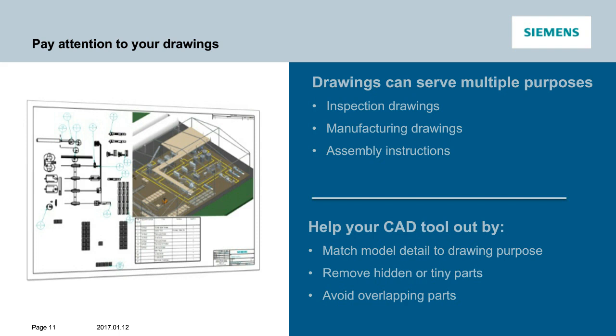The problem with detail is that it is costly in several ways. First, detail takes a long time to create. It's very gratifying to create a lot of detail, but it takes a long time to do it. Second, it takes a long time to display it every time you need to do so, so your computer has got to work that much extra. Too much detail can have a critical impact when it comes to drawing performance. Drawings must calculate every edge and then decide if they're hidden, shown, grayed, dashed, in this font, that font, some color, for every part, every time it's shown.